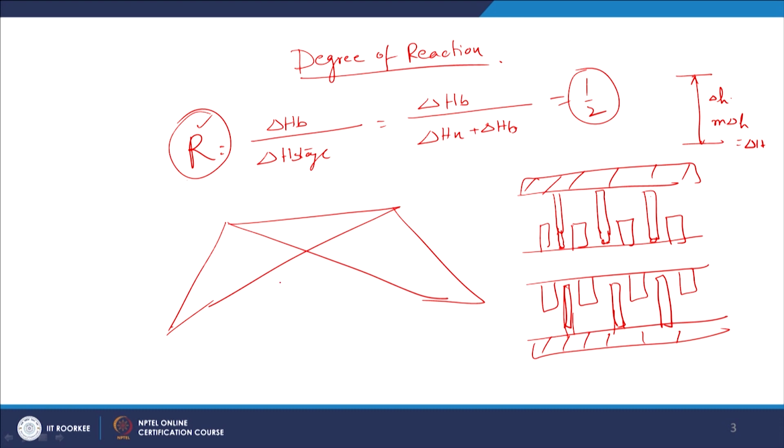velocity diagram for the Parsons turbine: V1, VR1, beta 1, U, VR2, V2, alpha 1 and alpha 2. So when we draw it, because the degree of reaction is half, V1 is equal to VR2, VR1 is equal to V2, alpha 1 is equal to beta 2 and alpha 2 is equal to beta 1.